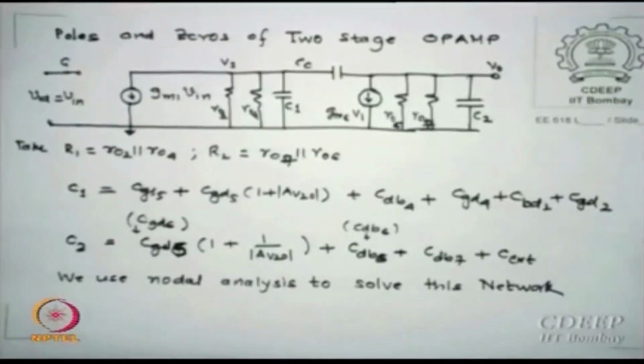Please remember one more thing, circuit wise you must know, unless the second terminal of the capacitor is AC grounded, that node does not receive any contribution from that capacitor, is that point clear? If a capacitor is sitting at this node and the other end is not grounded, it does not play any role, AC or DC. For AC it is ground, is that correct? So unless the other end is grounded, it does not add at that node.